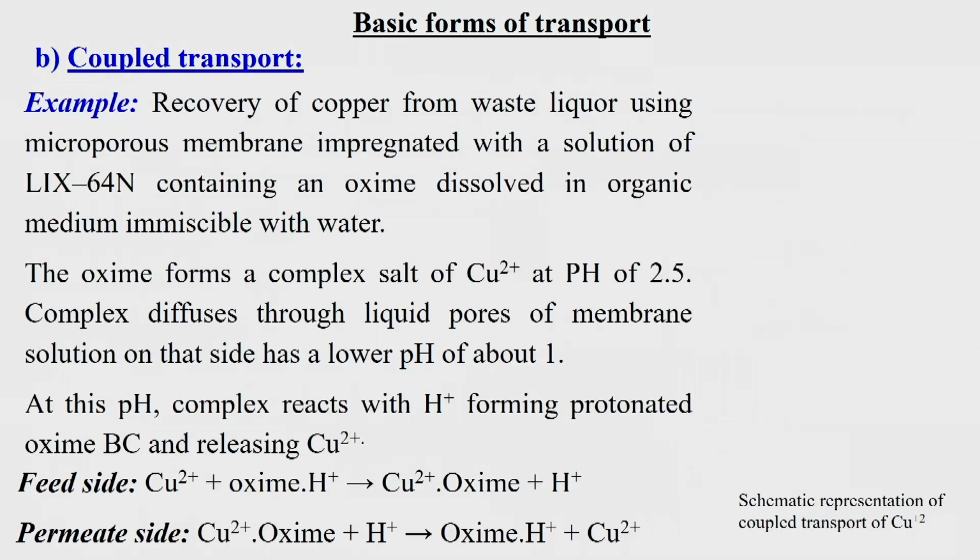And for the last, an example of this coupled transport is recovery of copper from waste liquor using a microporous membrane impregnated with a solution of LiX64N containing an oxime dissolved in an organic medium immiscible with water.